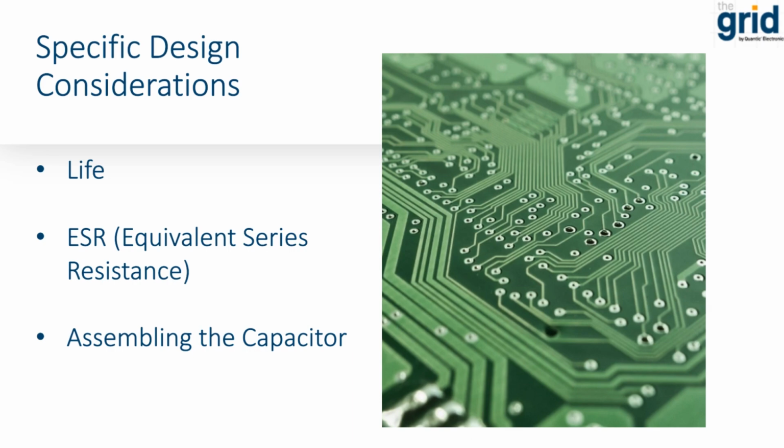Now, capacitors wear out or degrade over time, especially aluminum electrolytic capacitors, leading to decreased capacitance and potential instability. This wear out can occur while energized or during storage. Periodic inspection and replacement of some capacitor technologies are recommended to maintain optimal performance. Some capacitor technologies have an unlimited shelf life, ensuring they are ready even if the weapon has been in storage for an extended period of time.